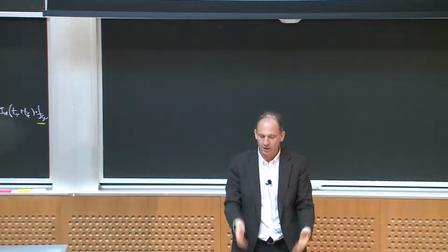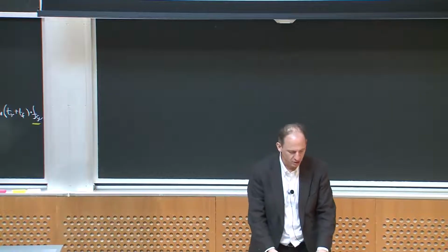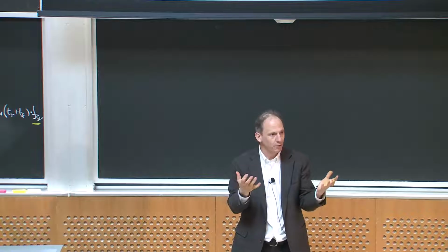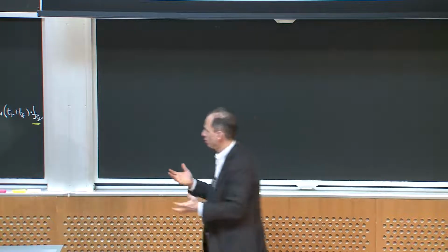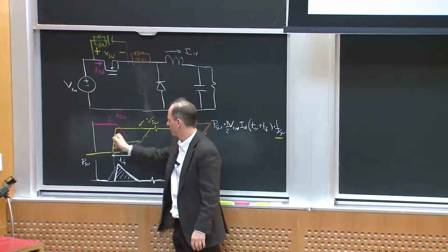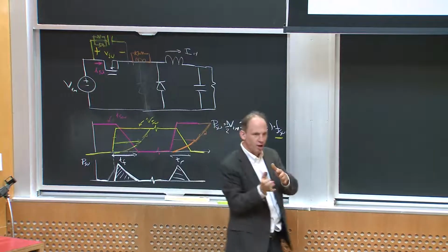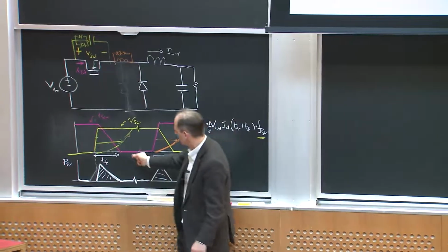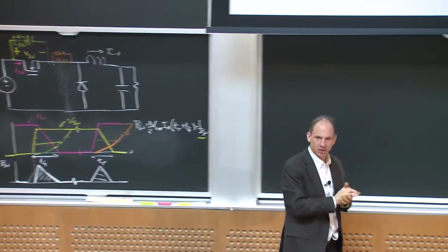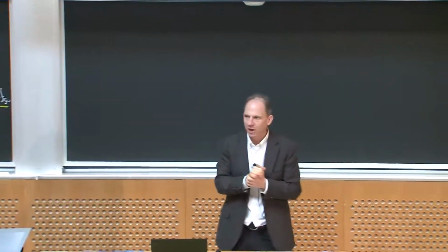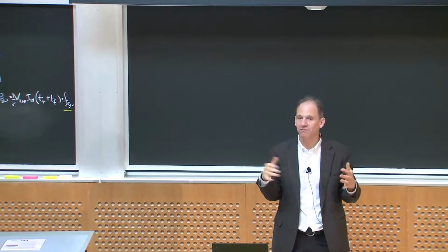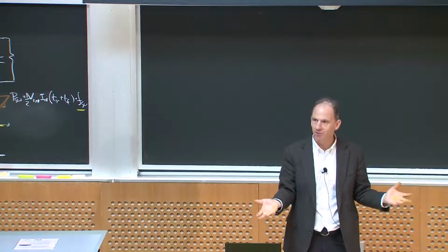They come up with circuits, either changes in the circuit design or changes in the control that will let people sort of get this so-called soft switching. This sort of pink and yellow transition we would consider hard switched. A soft switch transition is one in which you reduce the voltage and current overlap at the switching transition and get much lower switching loss. Okay? Now I say that many, many very high performance converters do this. This is a very common thing at the high performance end of the spectrum.